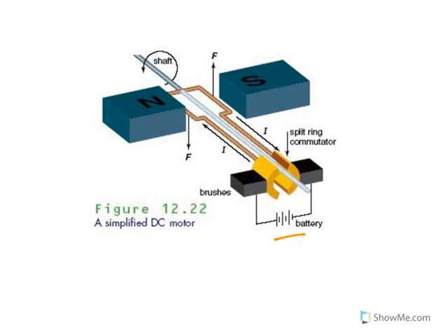Here's your battery down here, and your current's flowing there to these things called brushes. Usually they're made of carbon, and then they touch this thing here that's split. It's like a ring, but it's got a split in it, and so it's called a split ring commutator. At the moment, the current's coming in here, going around there, and going this way. And so we're getting our force in the down direction, like so, and the thing rotates.